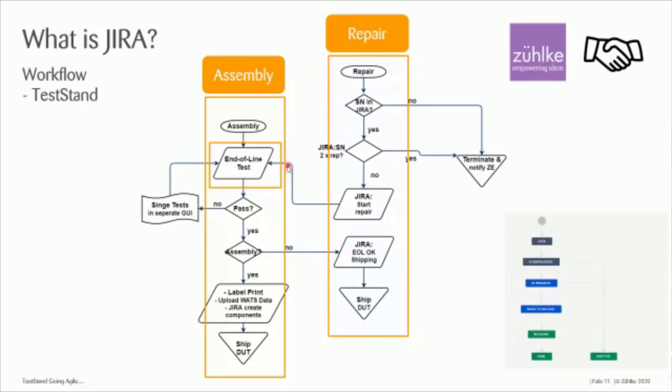Let's say my device does not pass all of the tests, so the device has to undergo like 47 tests approximately. And let's say it doesn't pass the brightness test, so the display brightness can't be passed. So you take it out, you repair the display and probably the PCB below it, and then it goes back into the end-of-line testing and you pass.